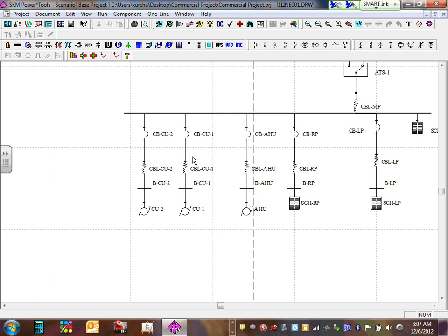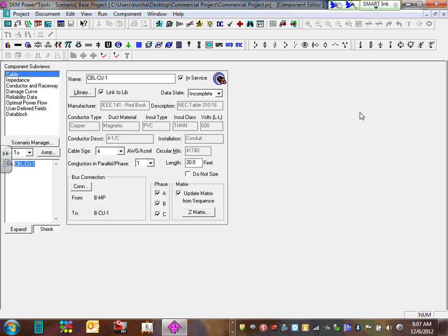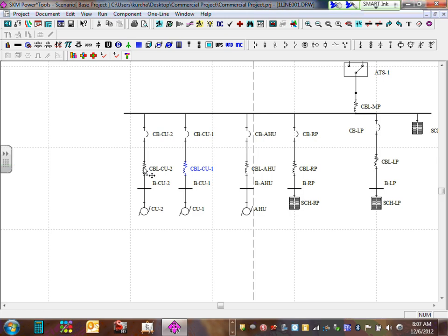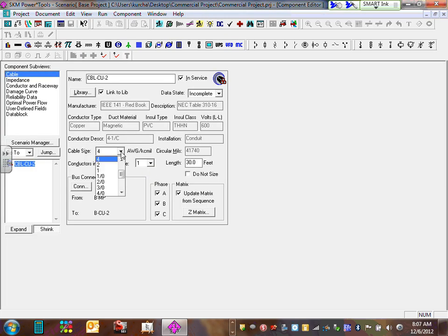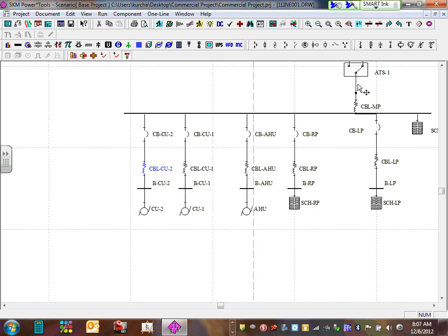Now, remember, we didn't size the cable though. So let's go, what did we say chiller number 1 cable was, number 4, right? So Aaron, can you give me chiller number 2 cable, please? Click on the cable. What was the size of that baby? Anybody else? How did you guys size it? How much? 6, number 6. The chiller number 2, future chiller. Did you guys get number 6? Okay. Number 6. Cool. Number 6 and close it. So my conductors are number 6.